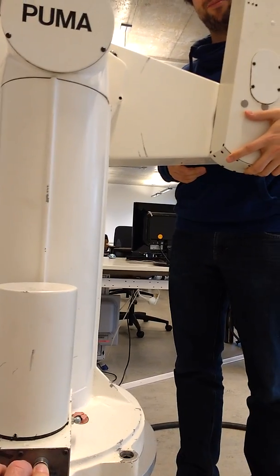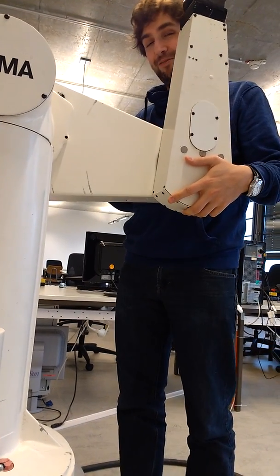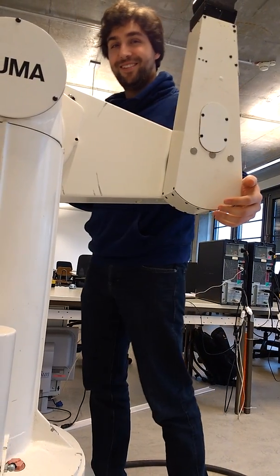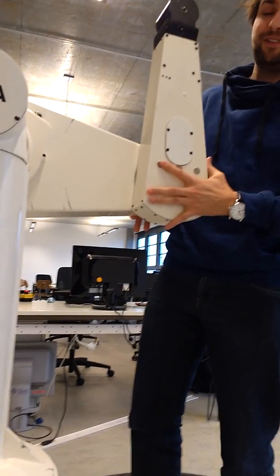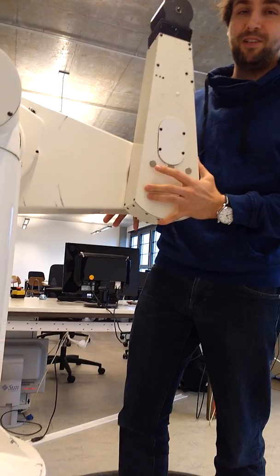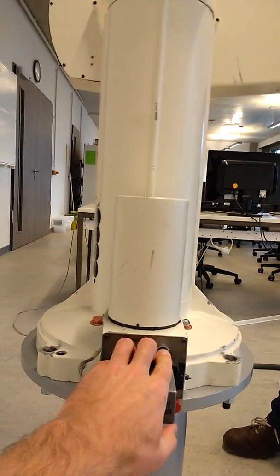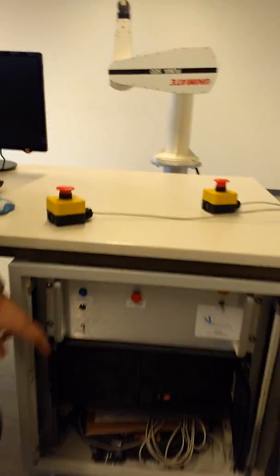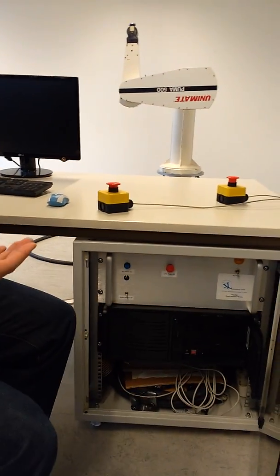But maybe you already switched off the amplifier. Okay. Do you still want to do it? No, it's fine. I think we demoed it. If you push the button, you could then move the robot, put it in zero configuration, then release the button again. And then when you're done with that, you can engage the brake release off button. So while running, you usually want this to be on brake release off.